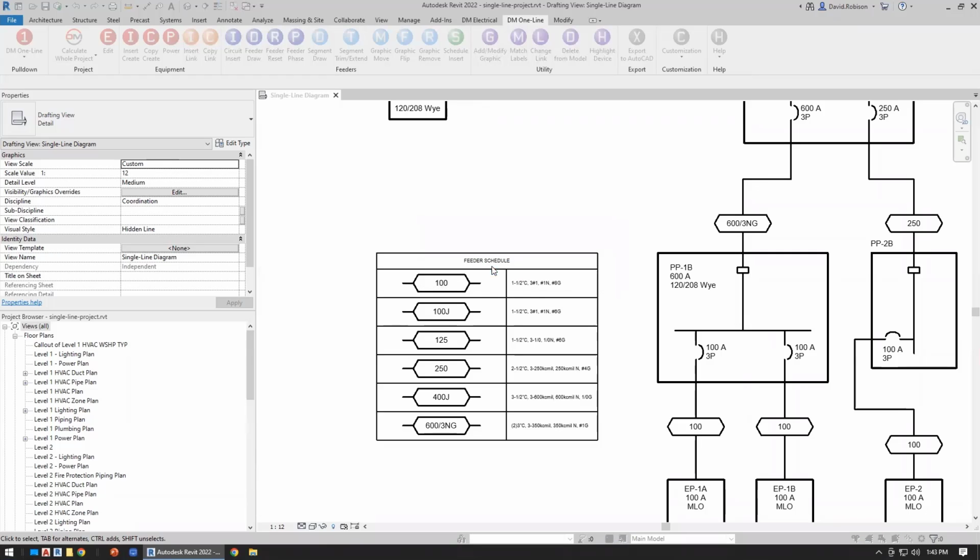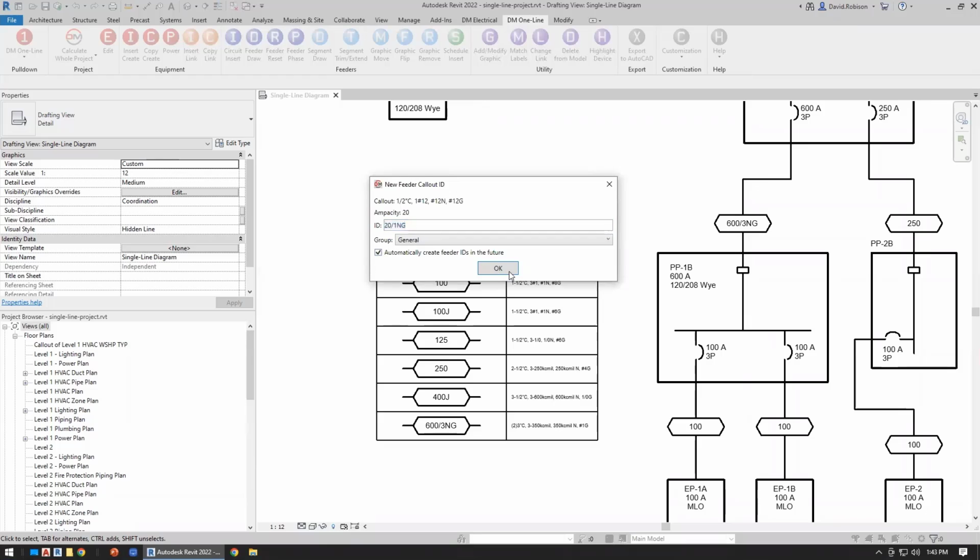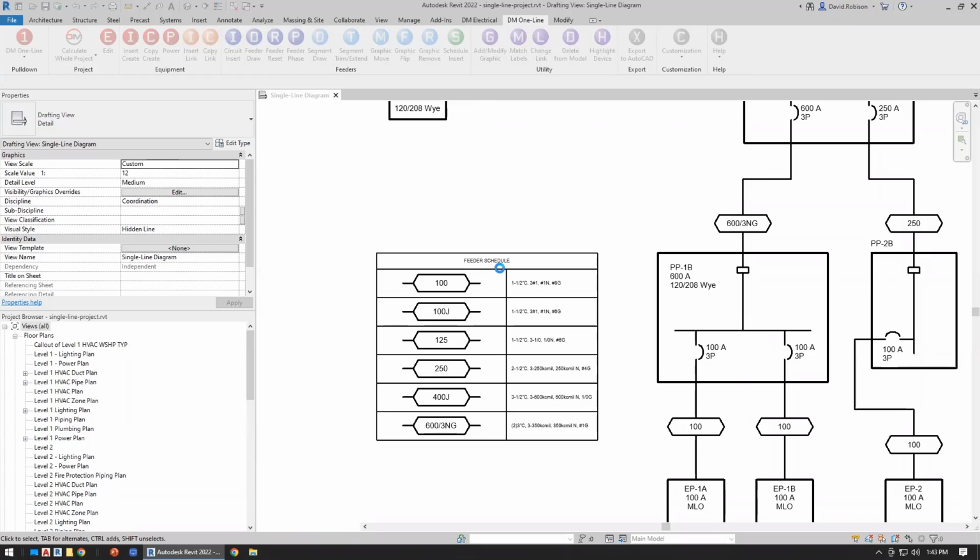And this is where, if you're happy with our formatting, you want to check this box so it stops asking you and just uses the default value. But if we were typing in something different, that way you could, as each one is generated, type in what you actually want that label to be based upon your system of creating feeder IDs. And then once this is done, we will have all of these updated with the new long feeder ID format. So there we go. It finished the calculation. And we've got the different labels being displayed there.